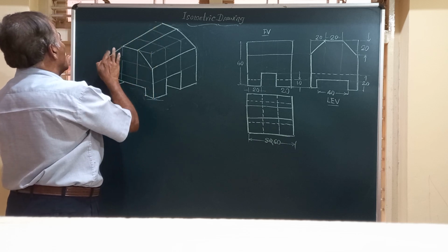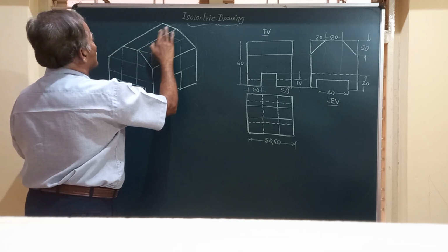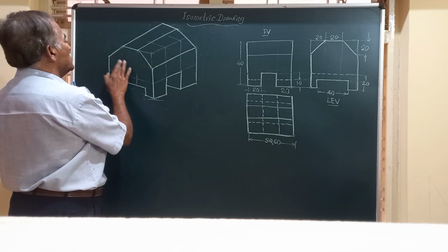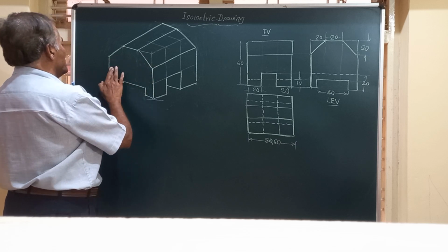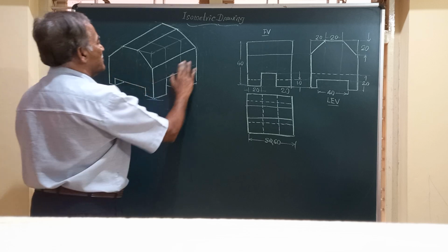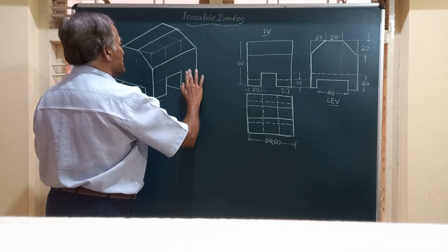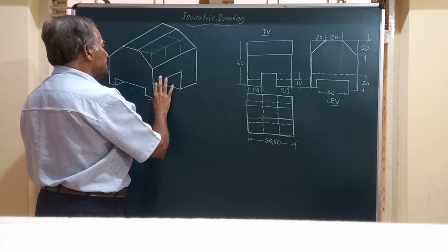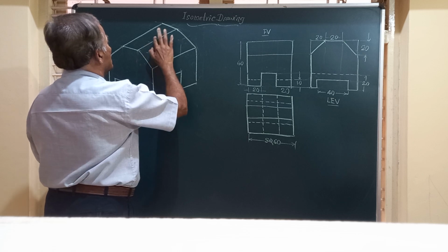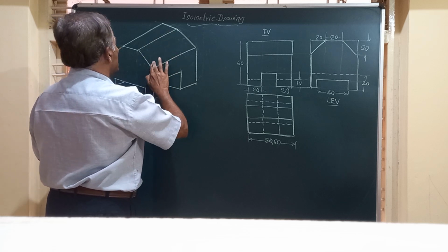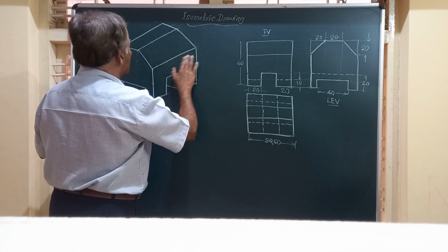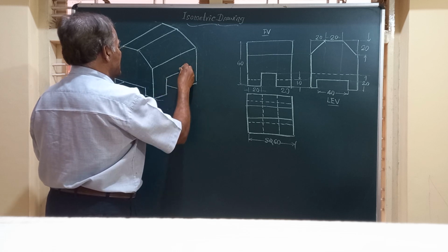By removing all these construction lines or unwanted lines, the learners or all the viewers of this will be able to get a clear picture of the isometric drawing of the component whose orthographic views are given. So let me remove all these. And if you want to retain them, you can retain them by very thin lines just visible to the observer. So friends, this is how your final drawing looks after removing all the construction lines and the inner details.